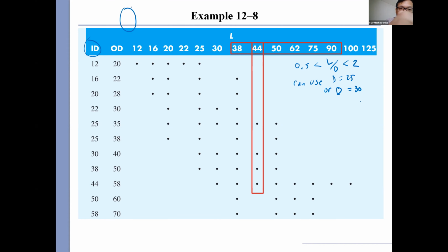If this is the bushing, which surface rubs against the shaft? Inner. Yep. Yeah, so that's where the interaction happens. That's when the heat develops. That's where the wear happens. So it's all about the ID, not the OD. The OD is just to tell you the thickness, and also it fits in a housing or in a hub with certainty.